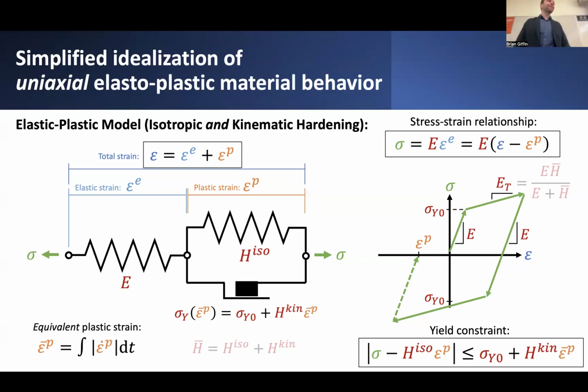And there were a few different ways that we could construct this model to include different behaviors that exhibited an apparent increase in the resistance to sliding, depending on whether you're choosing to put, let's say, some spring in parallel with this slider, which would result in an apparent increase in the resistance of this whole assembly to continued sliding of that slider element. And that gave us behavior that I referred to as kinematic hardening. It was equivalent to supposing that the actual envelope of the so-called elastic range of this representative model maintains a fixed width.